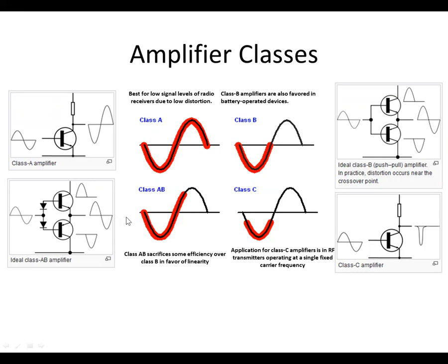So like I mentioned, the Class AB is a design to address that crossover problem. And one way that it can be taken care of is by the addition of a couple diodes here to compensate for that bias, forward bias voltage of the transistors, so you don't get the distortion at the zero cross that you did. And then Class C is just kind of like a pulse. It pulses on once you get over a certain threshold in the sine wave.